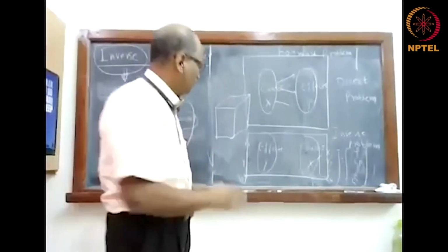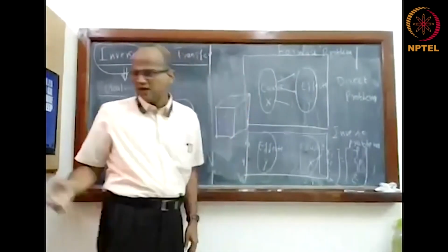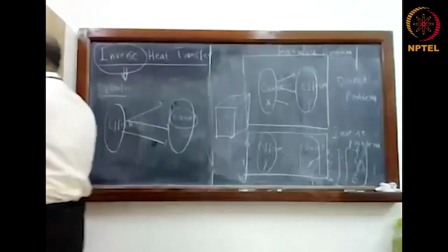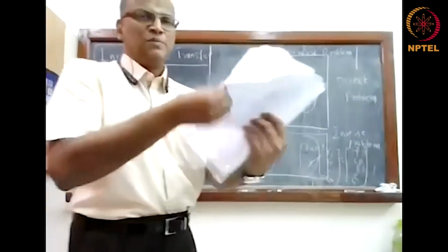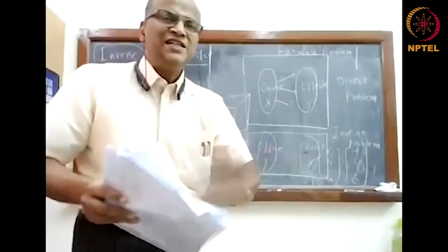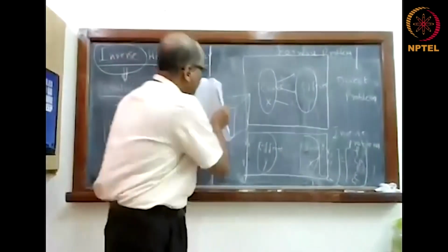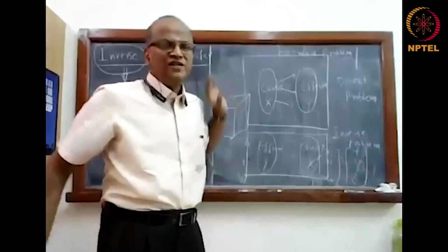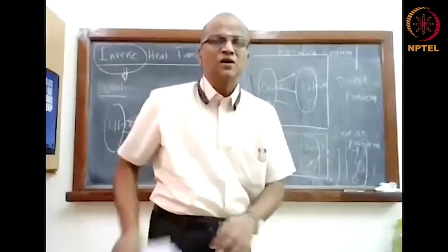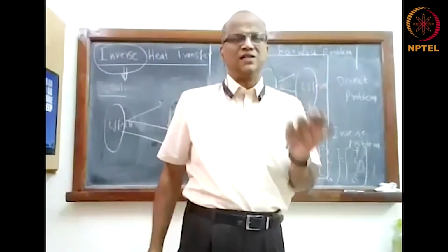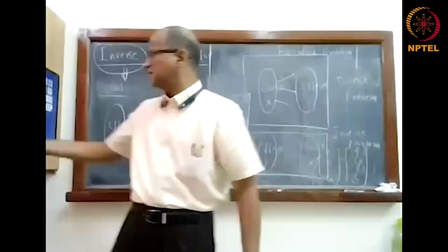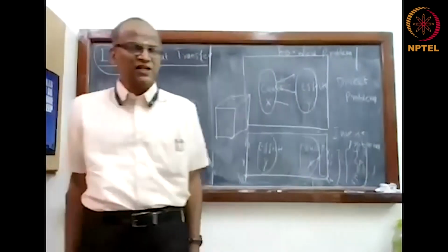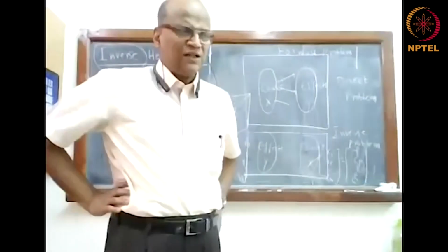Let's go even better. I can take some sheet. Okay, there is some plastic. You say, okay, this is some plastic sheet. There are sheets available which you can stick onto this. If it is heated, it is made of what is called thermochromic liquid crystal, TLC. Suraj is doing PhD on that. Thermochromic liquid crystal. The funda of that crystal is it changes color depending on the temperature.